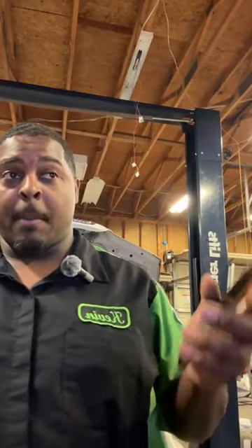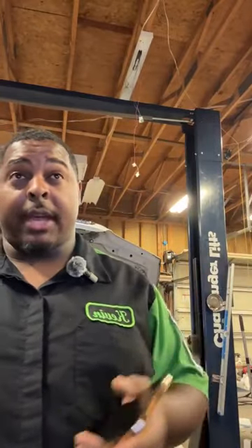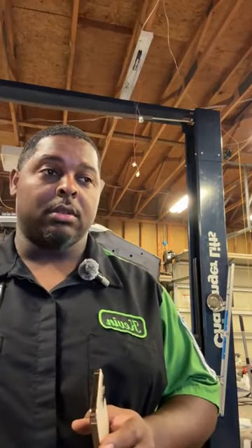Alright, so the PowerPoint that he's referring to in the 10th gens is on the lower right hand side of the steering wheel. There's two PowerPoints. A cigarette lighter and a PowerPoint, or both PowerPoints, however you want to describe them. So there should be a way, and we're going to look at the wiring diagram here and see if there's a way I can guide you to maybe accomplish what you want to accomplish without replacing the actual cigarette lighter or the PowerPoint.